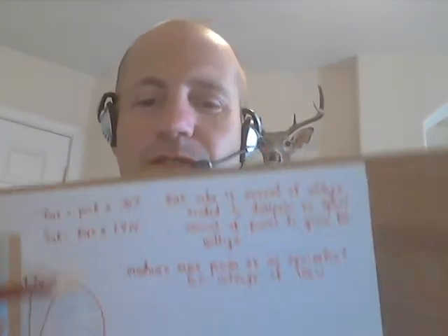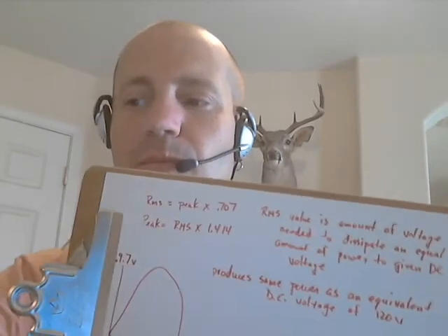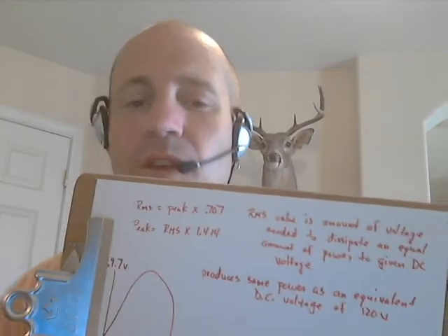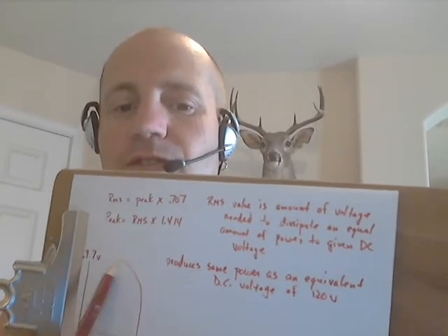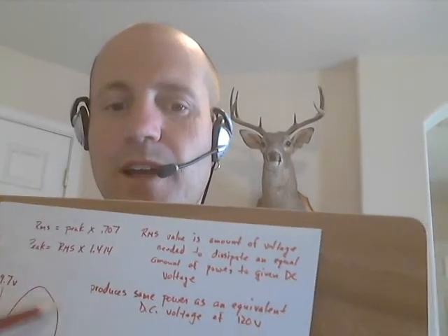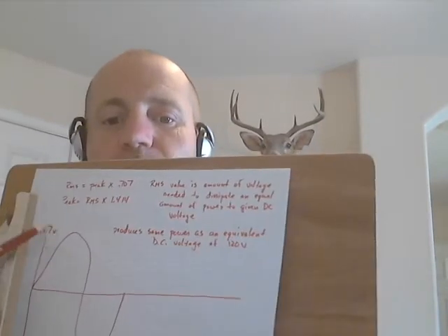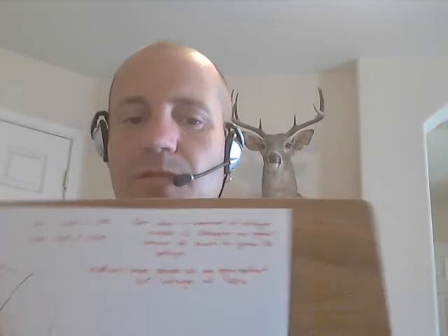Well, how do we find that? It's really not that difficult. In all actuality, when you plug into an outlet on your wall, you're plugging into an AC source that generates a peak voltage not of 120 volts, but actually this top positive peak right here, in other words, where it reaches its maximum positive voltage, is roughly 169.7 volts.